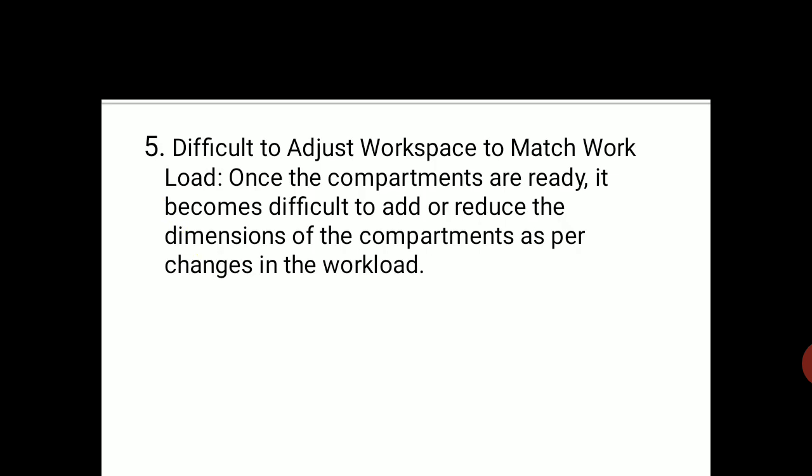The next and the last one that comes up is that it is difficult to adjust at the workplace or to match the workload, because once the compartments are ready, it becomes difficult to add or reduce the dimensions of the compartment as per the changes in the workload. So at times in cellular layout, it becomes difficult to balance the workload or workspace. You cannot manage it, and that time it proves to be disadvantageous for the manufacturer.